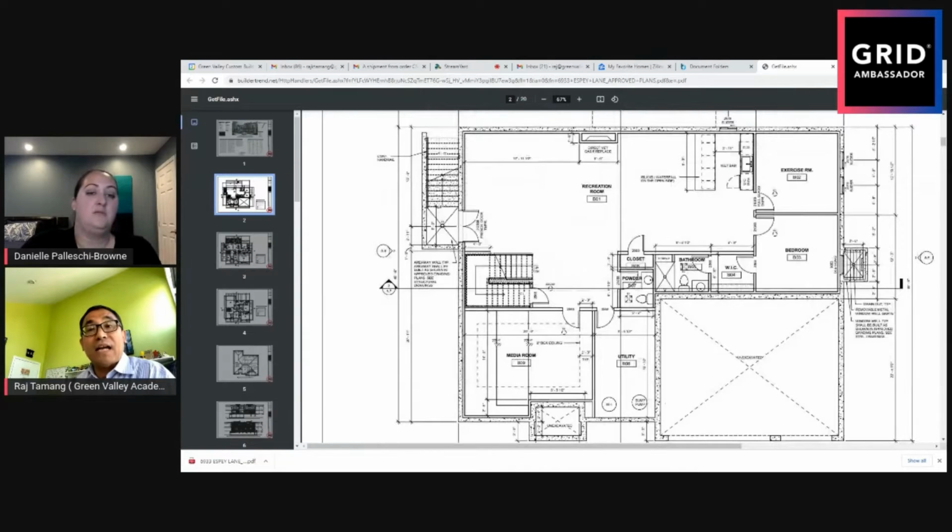So how do you know the thickness of the concrete wall? What's the thickness of the footing? How wide are the footings? All that information would be in a structural drawing. Yes. So really, you get a full idea just looking at even a plan like this: how thick the walls are, what they are made of, where they are sitting on the lot, what kind of topography is outside of that wall. You really do get a full picture of that.